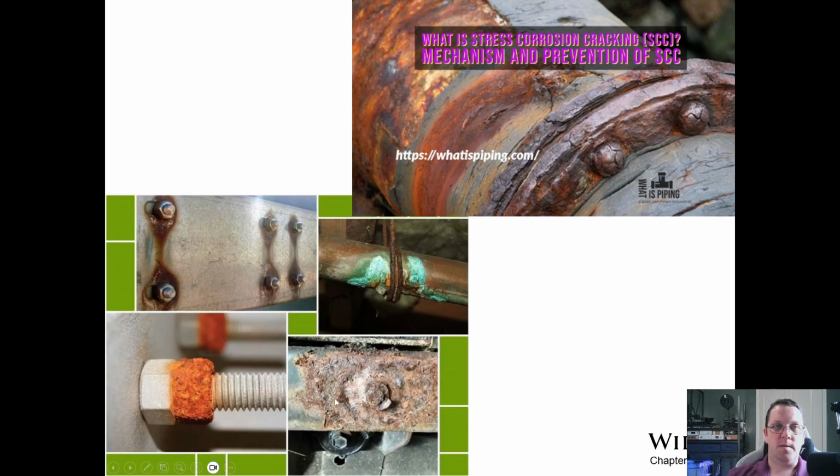And you have a coated surface, but you have some probably salt water or salt water vapor that has promoted corrosion on this surface. So there's a lot of different factors that may come into play for something like this, creating a difference in electrical potential between them, and with the presence of any moisture at all, having a pairing of that nature.